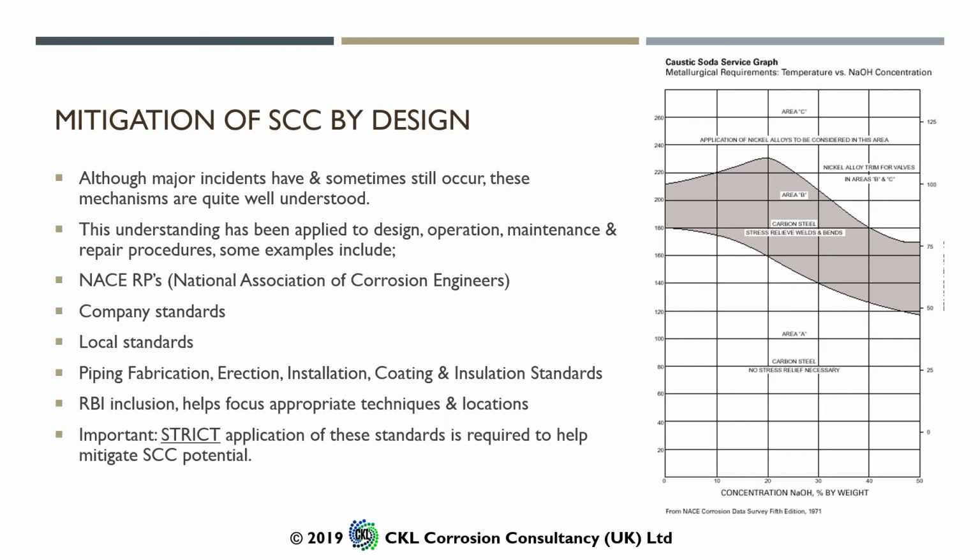With regard to some of the cracking mechanisms which we'll cover, some are external environmental stress corrosion cracking, such as chloride. Chloride stress corrosion cracking from an external environment under insulation is quite a big issue. So this is where the coating and insulation standards and cladding become very important. We'll cover some of that in a bit of detail when we go through this.